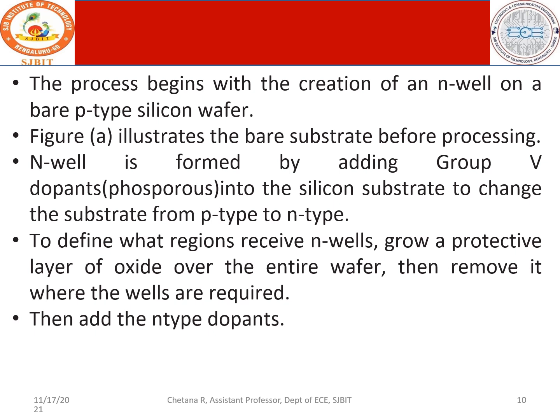So this starts the N type of dopants. So understand, identify the region where you want to create the N well structure. The other area where you don't want the N well structure is already safeguarded by the oxide. So even though you make the N diffusion fall on the oxide layer, the bottom layer is safe and it is not going to get contaminated.